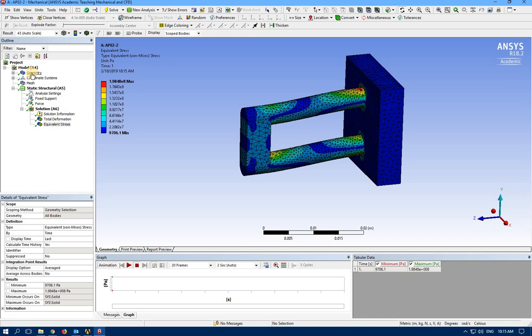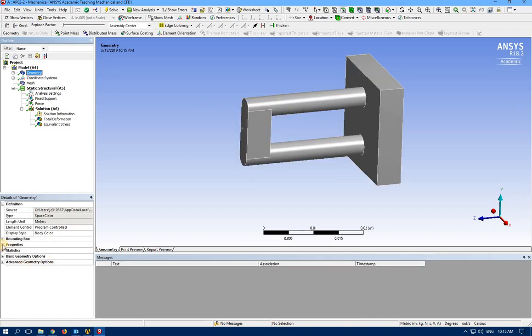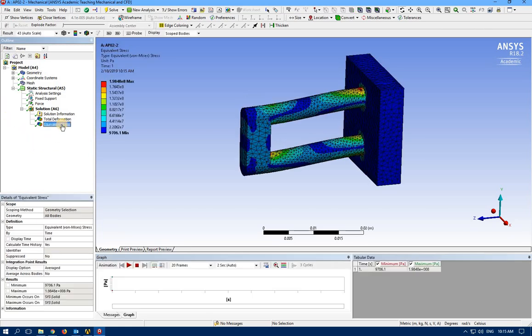So I select geometry to find mass, properties, mass. As you can see, there's an empty box here. If I select this one, there's a P here. So parameter is selected for mass. One of the output parameters, mass. The other one can be stress and maximum stress. Here we can select it as a parameter. So I have two input parameters, the diameter of the top and bottom cylinders, and two output parameters, maximum stress and mass of the whole design.